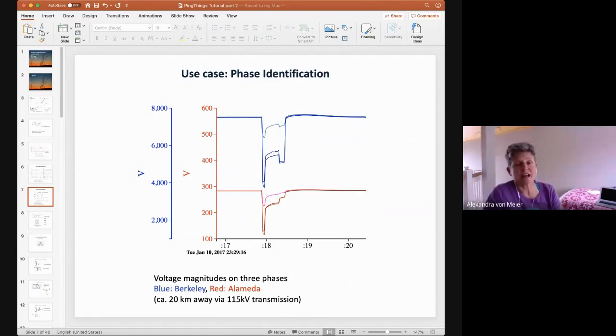But having said that, matching voltage magnitude disturbances from different locations, if you have sufficiently granular data, is a pretty powerful tool. And a lot of the work that Mohini has been doing with analytics, with our micro-PMU data, is basically doing fancy statistics with correlating these voltages and their disturbances. And that is all made possible by the time alignment and the fact that we got 120 samples per second here. You couldn't do this if you just got data once every second, or probably even 10 times a second would be hard to get this kind of confidence.